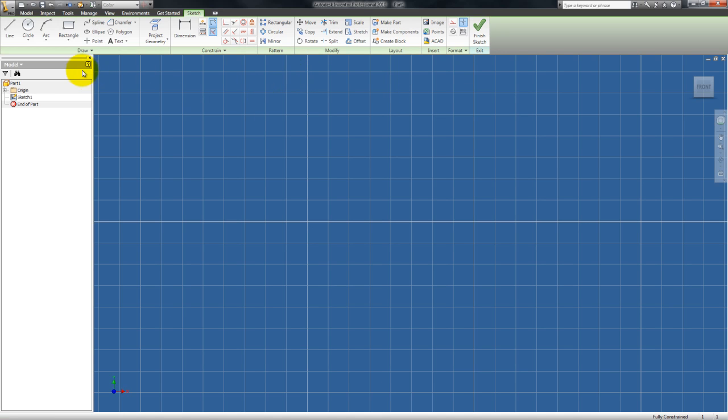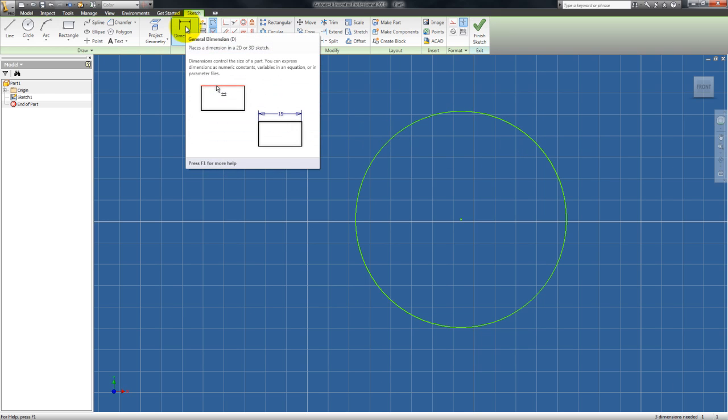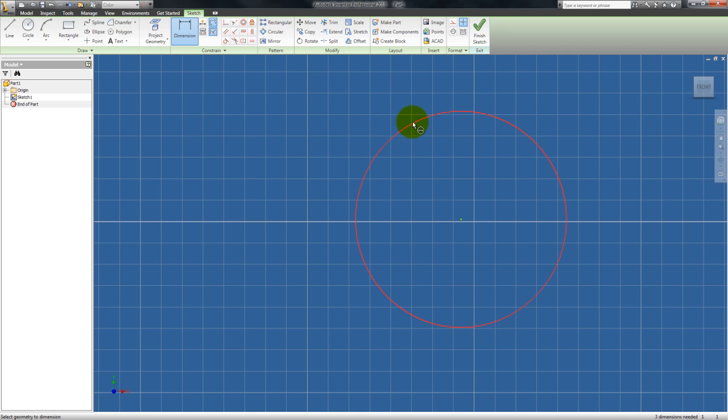Okay, so you're drawing a circle, so we click and draw, but we don't really know what size this circle is, and we want it to be a specific size, so we escape from the circle command. So now we have a circle, and we're going to constrain it. One easy way to do that would be click General Dimension, so D, click Dimension, then we click the circle, and it will give us a diameter. So now we have diameter, and it's 1.266.